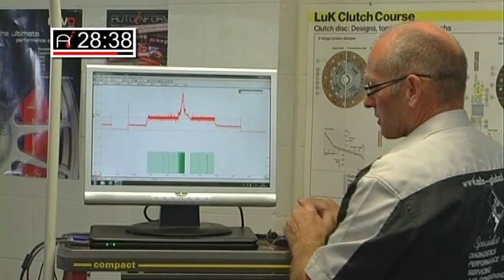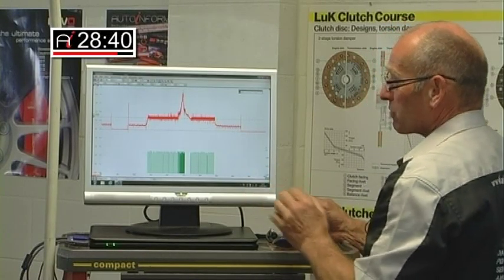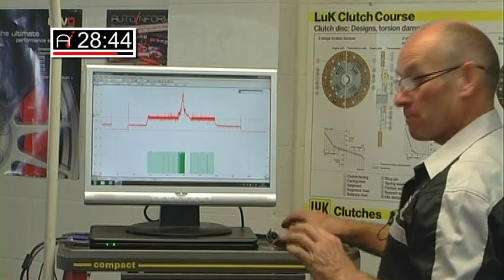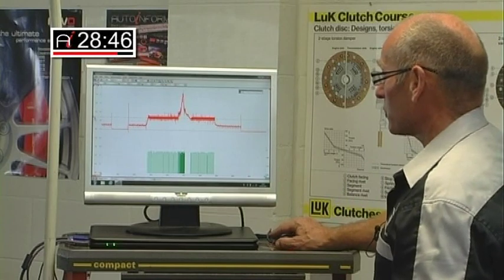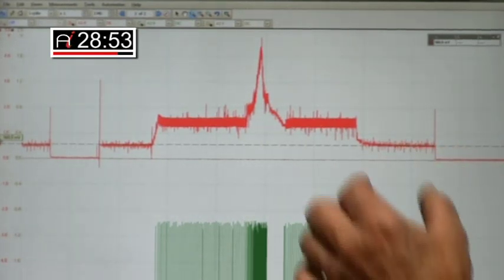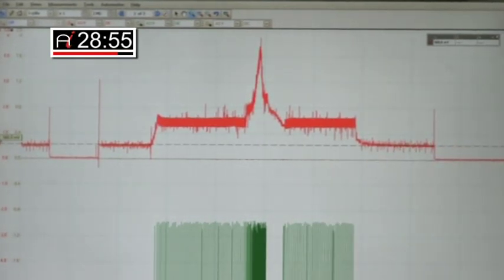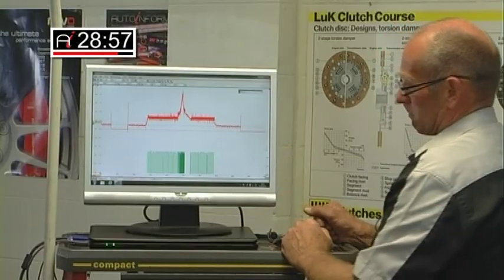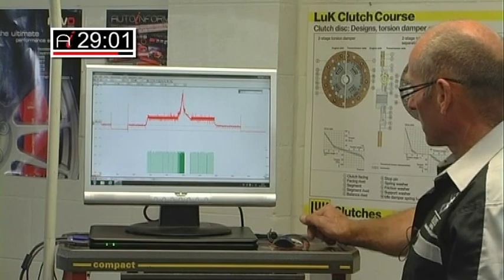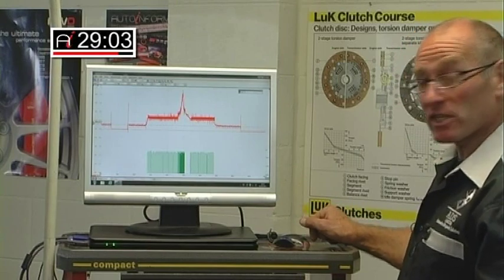Decay can be assessed, the time it takes for the pressure in the rail to diminish back to 0.5, which is zero pressure. 0.5 does not represent a pressure at all, it is a zero. And you can see from that it's taken about 5-8 seconds or so of time to diminish. Bosch CP1's around 9.5 seconds. So I don't anticipate any internal leaks either.